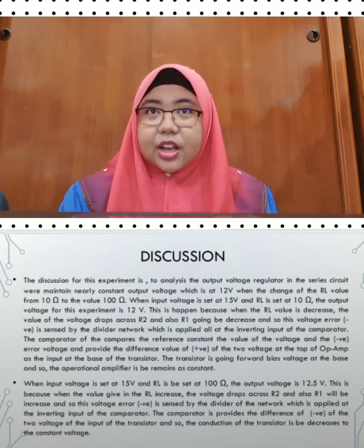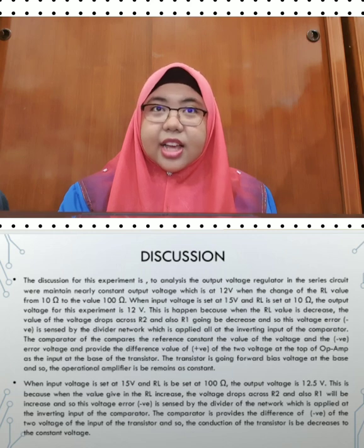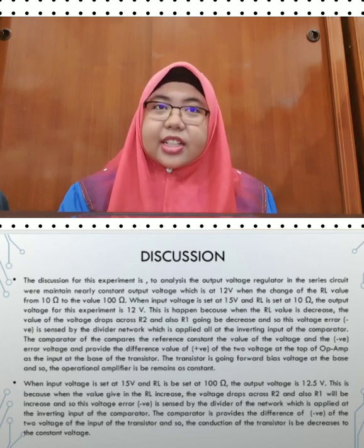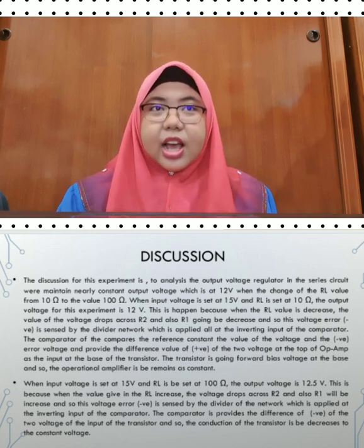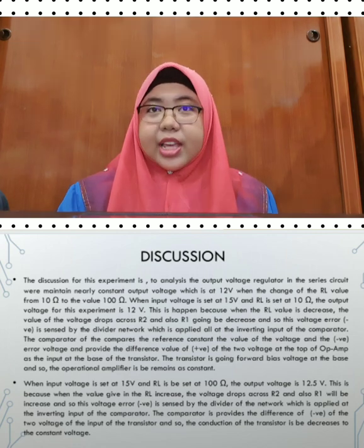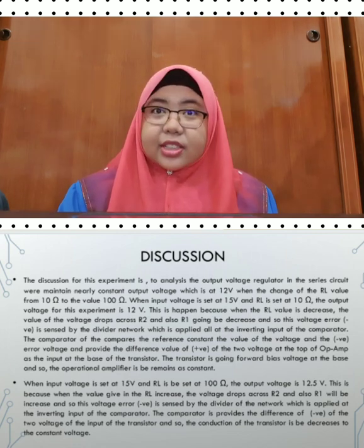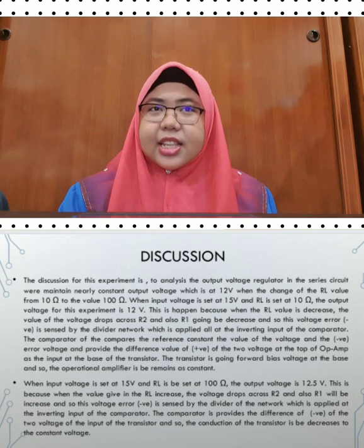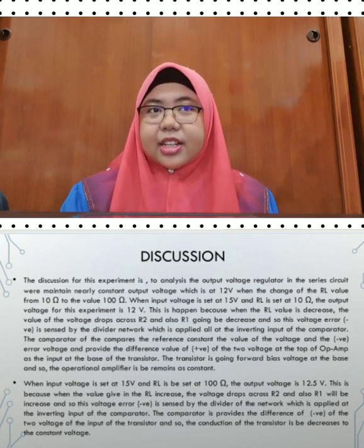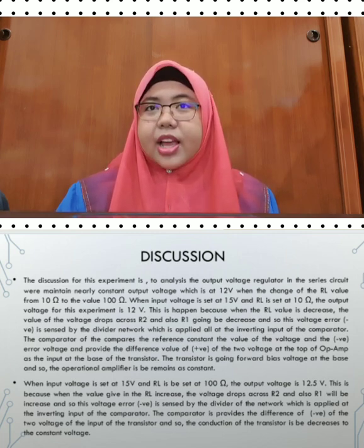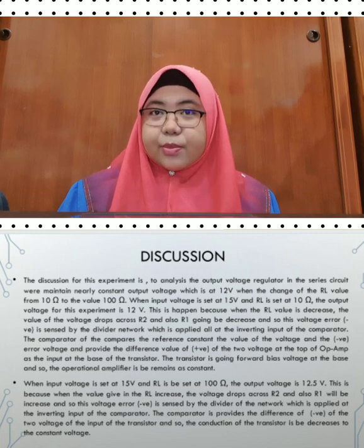This is because when the value of RL increases, the voltage drop across R1 and R2 will increase, and so the negative voltage is sensed by the divider network, which is applied at the inverting input of the comparator.